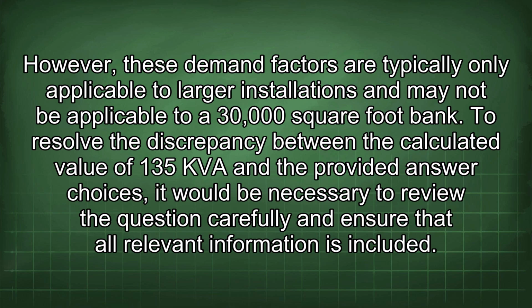However, these demand factors are typically only applicable to larger installations and may not be applicable to a 30,000 square foot bank. To resolve the discrepancy between the calculated value of 135 kVA and the provided answer choices, it would be necessary to review the question carefully and ensure that all relevant information is included.